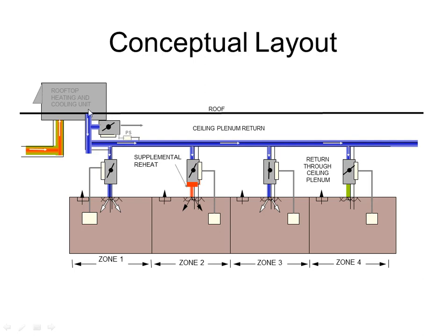Now, how the rooftop unit reacts to these temperatures is based on the set points of all the temperatures. All of the zones have their own set points, and they each have their own space temperature sensors. So if you look at this case, it looks like 2 of the zones are calling for cooling, one's calling for heating, and then one is in vent mode. So because there are 2 zones calling for cooling, the rooftop unit would actually be in cooling mode. Because of the vote between the zones, there's more call for cooling. The rooftop unit goes into its cooling mode.